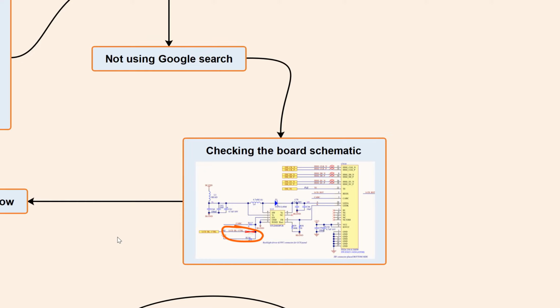The only difference between this screenshot and the previous one was this red cross, which was indicating the absence of resistors in this area of the circuit, which means that when I was toggling the LCD backlight control pin up and down, it was doing nothing because it was basically disconnected from the rest of the circuit.